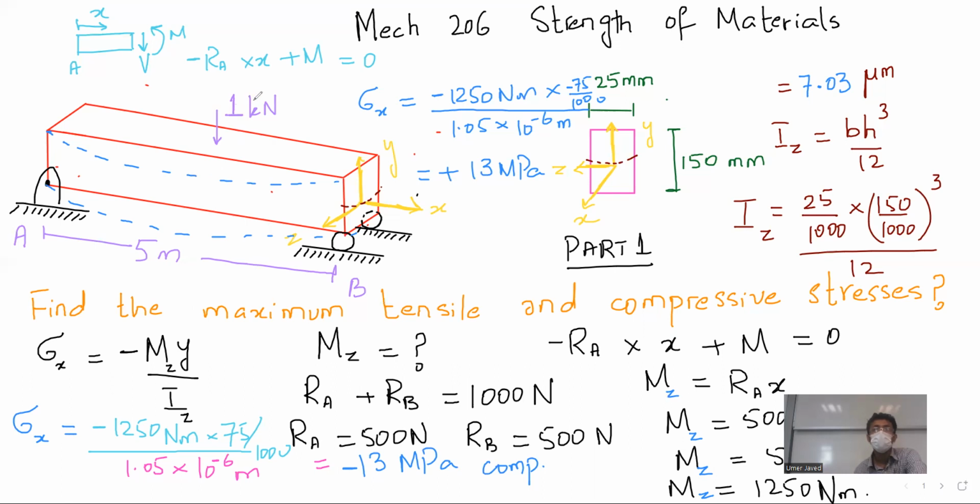You see this purple 1 kilonewton? In an exam setting, a very important comment. If I put the moment from the bottom and I remove this moment, now the moment is acting like this. The beam is bending like this. So the moment will be negative, right? Are you getting my point? So it depends on the direction of the force.